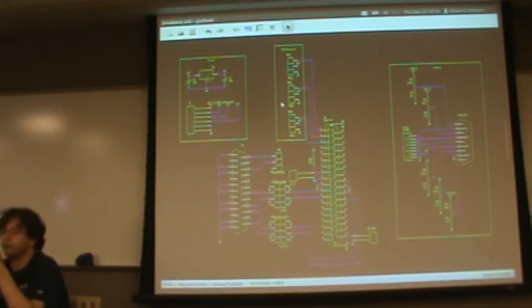Second of all, the schematic is capturing something that is different from the PCB. The PCB is a particular instantiation of the design. This schematic design exists independent of the printed circuit board. There are thousands of ways that I could lay out this board for different applications, but it would still have the same function, and that's what the schematic captures.